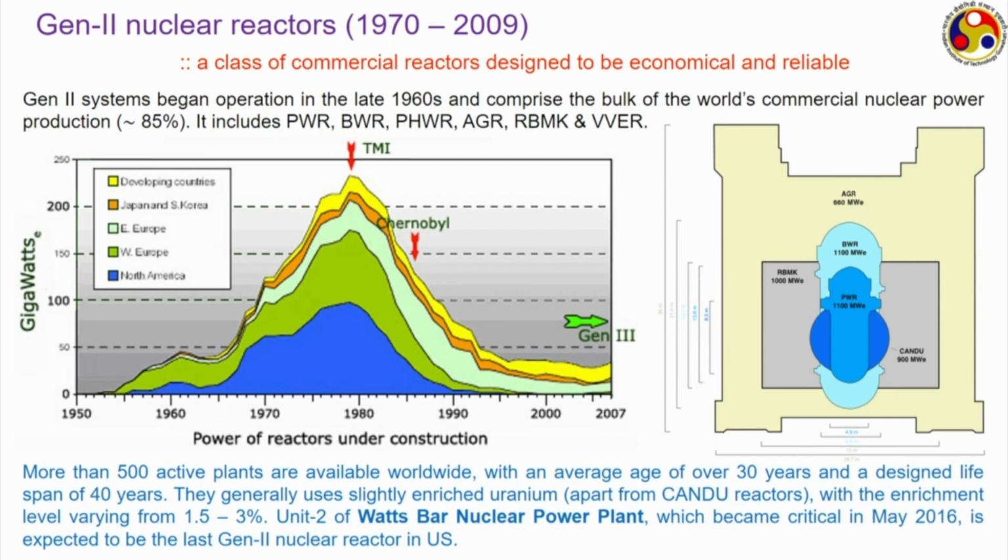And AGR, it is gas cooled reactors. So, the coolant is gas, huge amount of volume requirement. So, while producing about half of the power compared to PWR, you can see the volume is substantially larger compared to a PWR. But of course, it has its own advantage, like gases are generally cheaper and easier to handle in certain situations, and also there is no saturation temperature kind of restrictions with gas cooled reactors compared to PWRs or PHWRs.